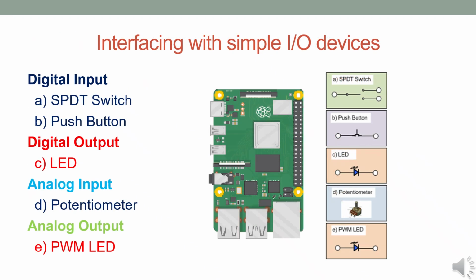When working with a Raspberry Pi, simple input and output devices allow the system to interact with the physical world, enabling it to sense events and control external components. The GPIO pins act as the interface for these devices, and by using Python with the gpiozero library, we can manage them in a simple and intuitive way. GPIO0 provides high-level classes for each type of device, which means we don't need to manually configure pins or write complex low-level code. Most of the setup happens automatically in the background.